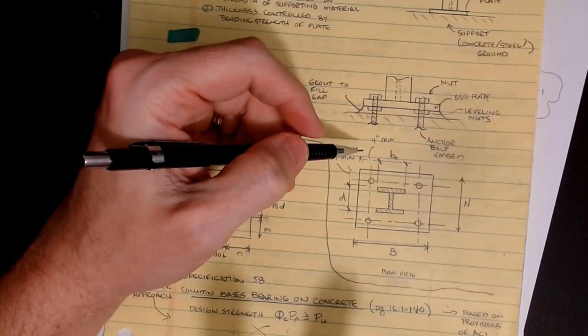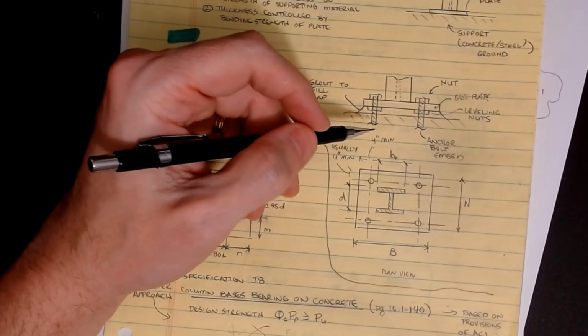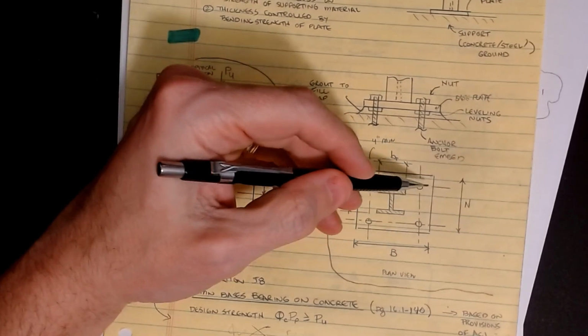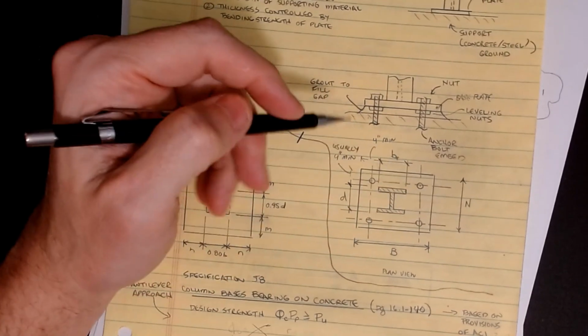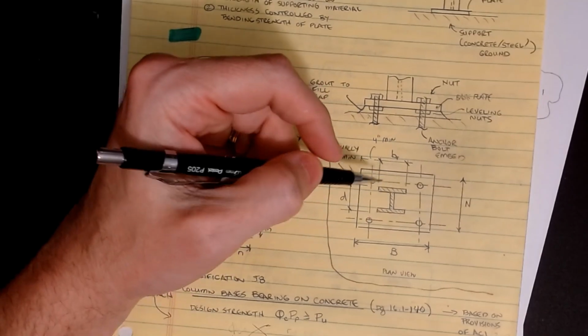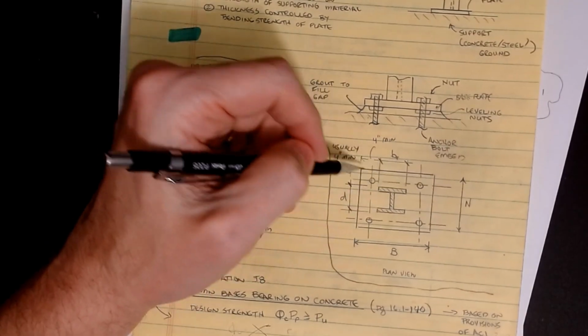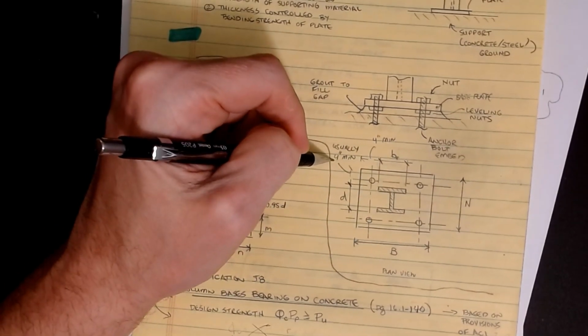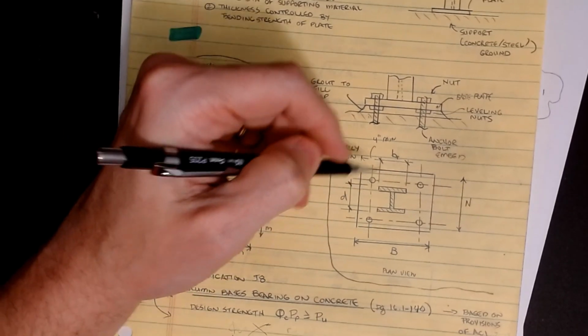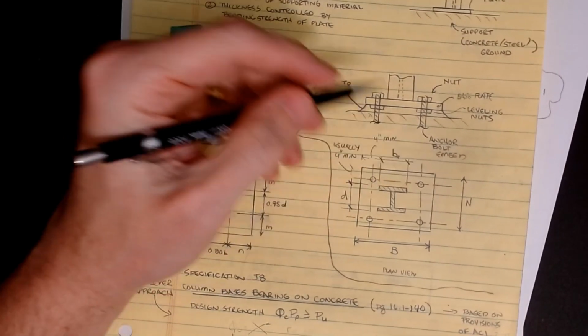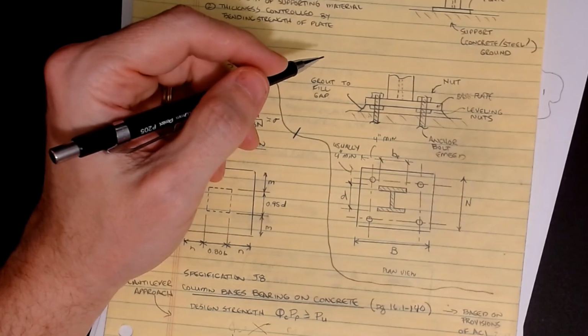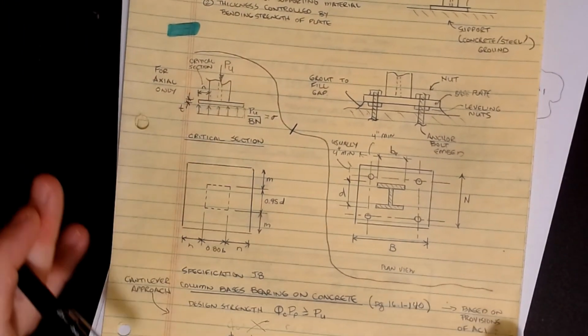Again, this is a rule of thumb. You still have to confirm everything. But if I'm just trying to get a rough size of what this plate is, and is it going to be a problem for my loads on it, I can get a quick guesstimate on the size of the plate based off of this: add 4 here, add 4 on the bottom, and then of course you add 4 on the sides as well to get those dimensions. Again, it's a rough check that we're going to look at.